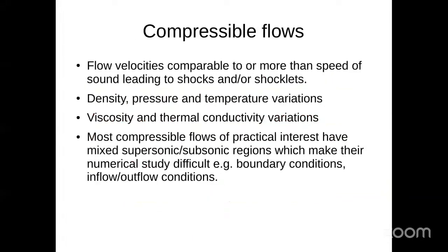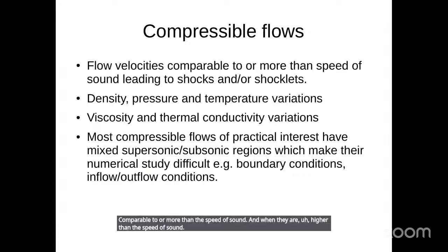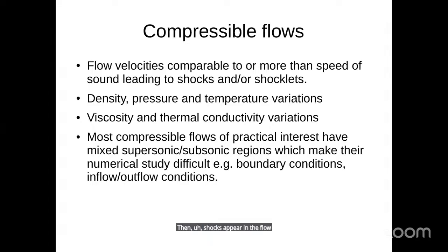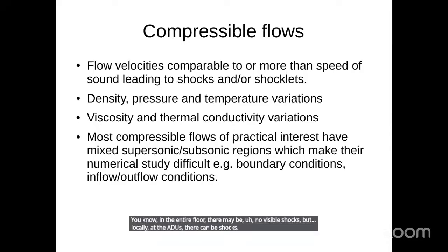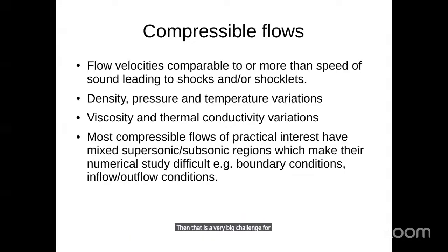Now, compressible flows have challenges because the flow velocities are comparable to or more than the speed of sound, and when they are higher than the speed of sound, then shocks appear in the flow, and also there can be shocklets, which are features of turbulent flows. That means near some eddies, or at the borders of adjacent eddies, there can be small shocks, even though in the entire flow there may be no visible shocks, but locally at the eddies there can be shocks. That is a very big challenge for numerical simulation.